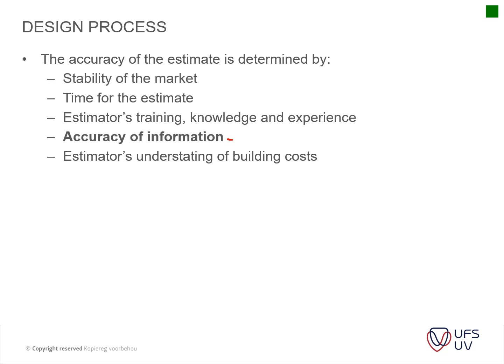So we actually saved a lot of money because the tiling area was such a large area. We could rather put in the PVC expansion joint instead of the stainless steel one, and we still got the same look and feel by just looking at the color of the PVC one that we put in. So that is options that one can actually look at when you do your estimation.